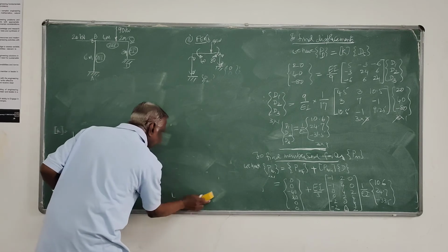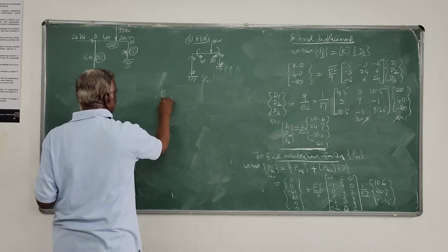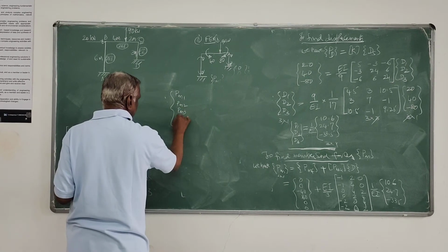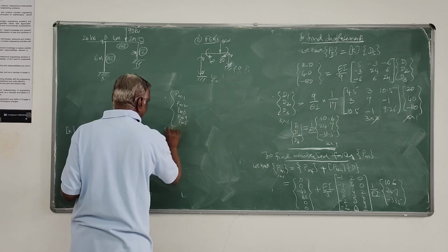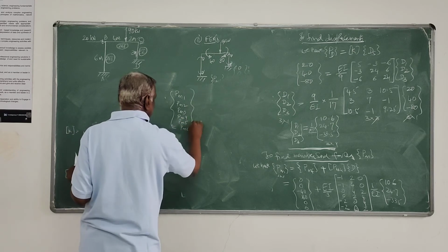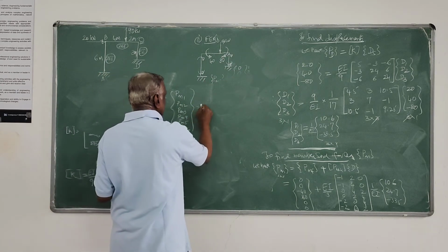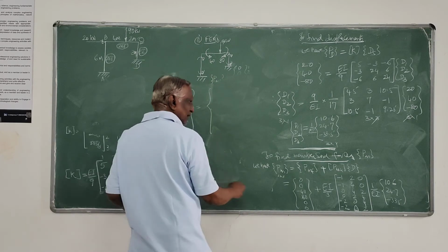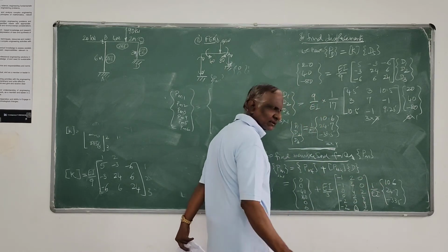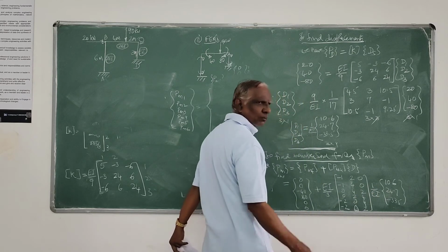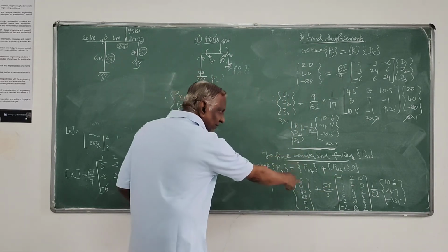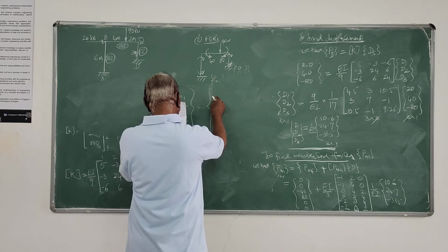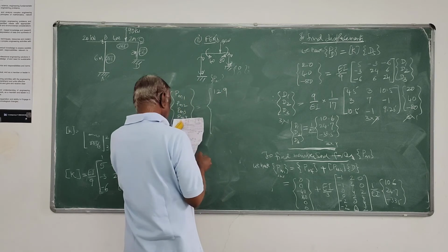So therefore, the PM matrix is nothing but PM1, PM2, PM3, PM4, PM5 and PM6. That is the 6 end moments. If you simplify, I have simplified the value, because you can easily multiply. Minus 1 into 10.6, minus 10.6 plus 2 into 24.7, that divided by 3 plus 0. If you do that exercise, you will get here 12.9.